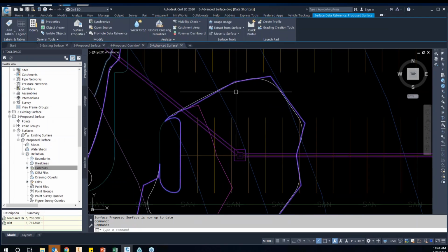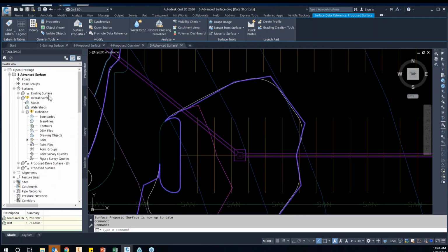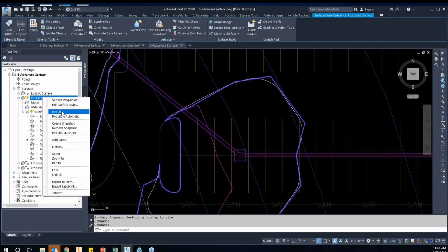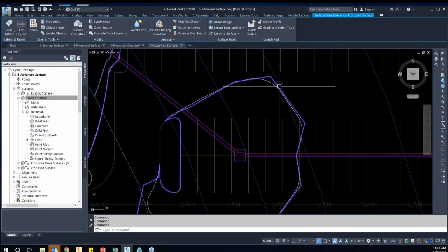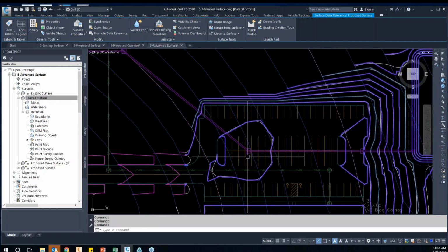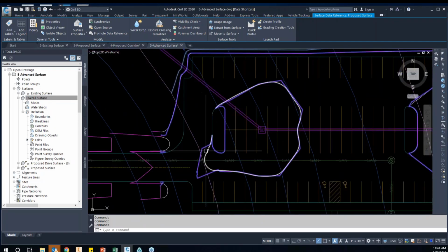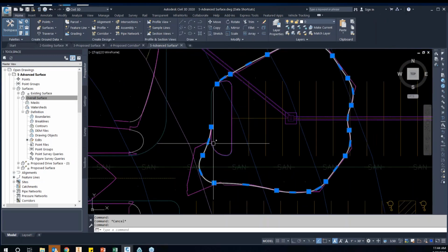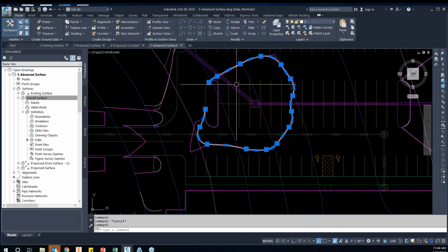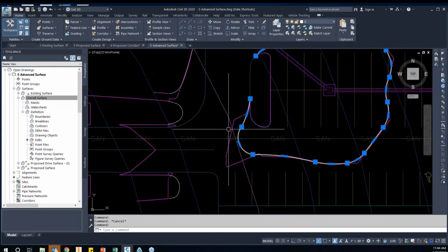All right, so that's that proposed surface there, okay. I have not updated my overall surface yet, okay, which has that surface pasted into it. So I'll go ahead and right click and rebuild that one. Okay. And now you'll see that it reflects this inlet incorporated. Okay. So now this line work here that I had, okay, best fit sort of represents that contour. Okay. And so, you just have to create that line for yourself, but I already have that line available. So I'm going to go ahead and utilize it.